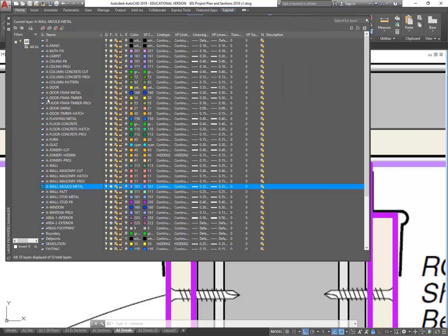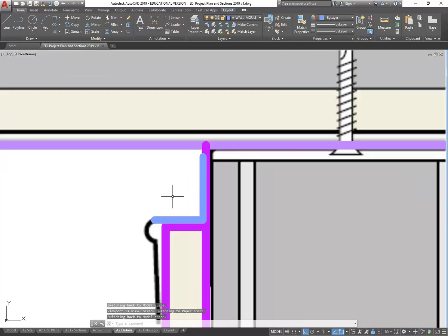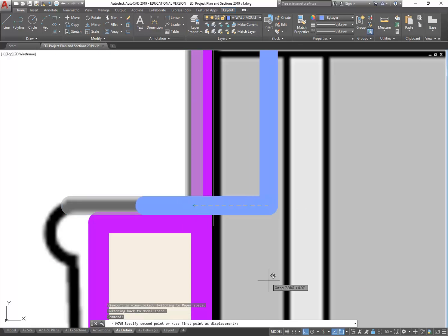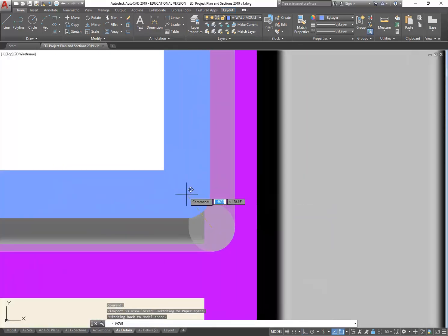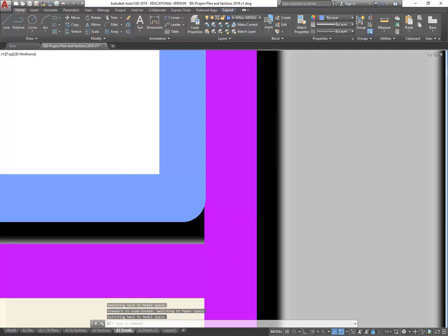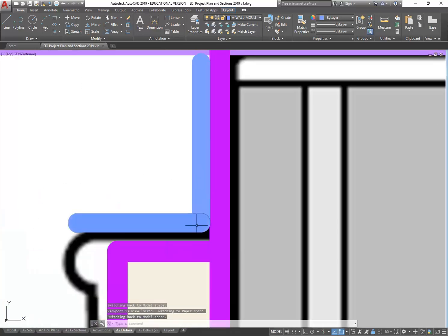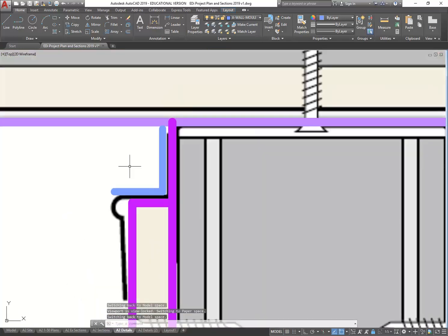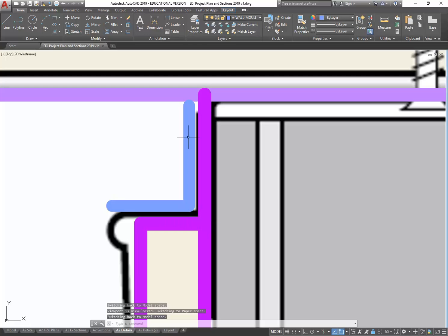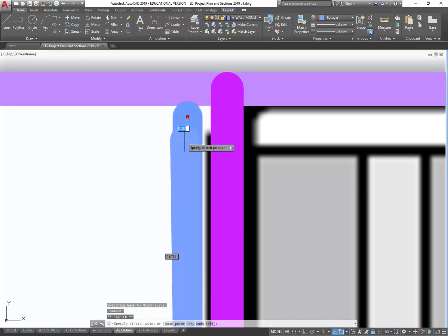Well, I do want to keep it at 0.35, so then what you'll probably do is cheat a little bit and bring these out, and again, these drawings are not true to life. It's not the way they'll build it. No builder is going to get up there and measure a quarter of a millimetre, which is sort of the level of detail we're looking at. If you measure these distances, well, okay, it's a couple of millimetres, but they're not going to measure that. They just put it in there and make it fit. So you just want a gap to show that these are two different lines. Otherwise it's just a big blob of ink when you print it and no one can tell what it is.